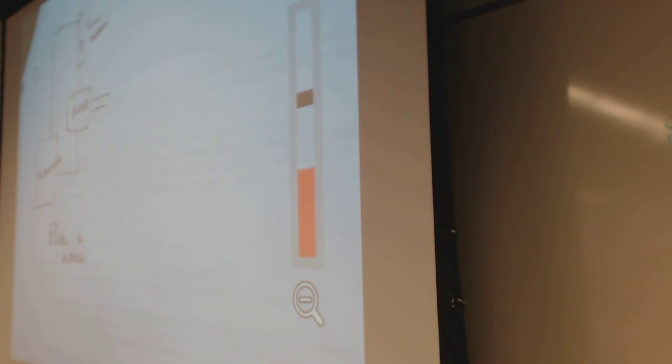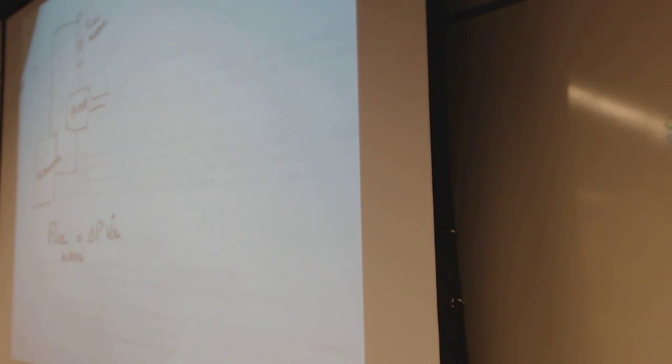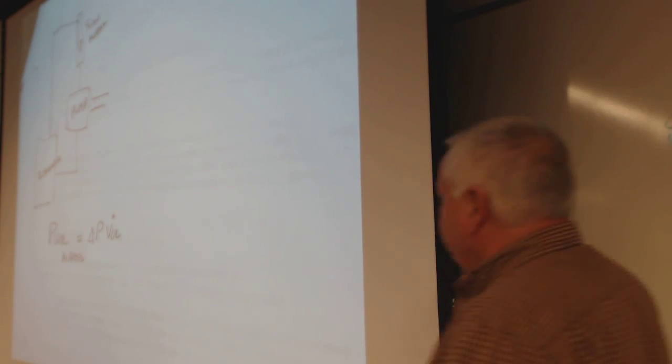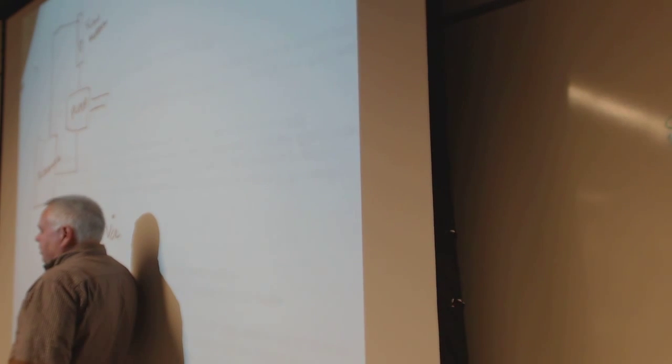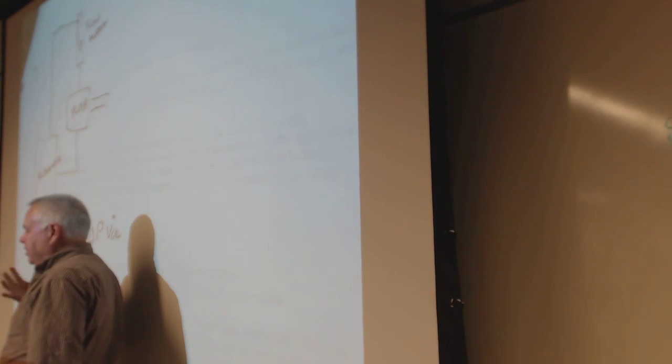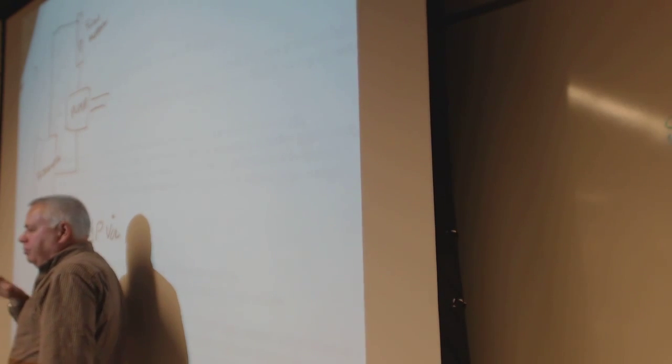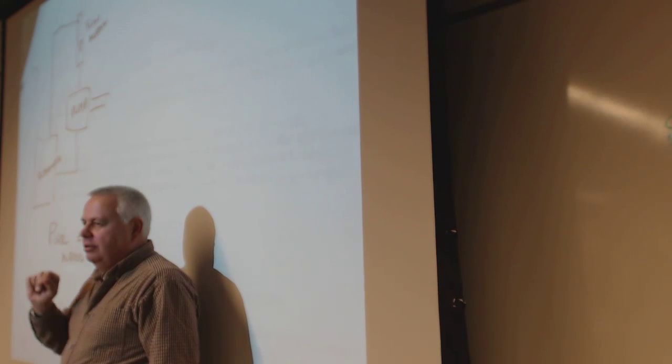The power in the water is, and you remember what the water power might possibly be? It was in your test. Delta P times the volume flow rate. Pressure times the volume flow rate. We are going to do it for a number of different pressure points: free flowing, 20, 40, 60, 80 psi. So each group will have 5 data points.